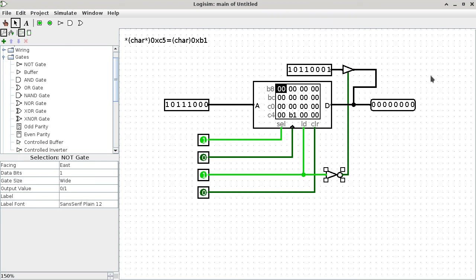On the other hand, when we are writing, which means the LD is going to be a 0, then we're telling the control buffer, okay, let's mirror whatever your input is to the output, because it is in a write cycle that we need to connect the input pin to the data pin. So this is the fix to that problem. Are we good so far?